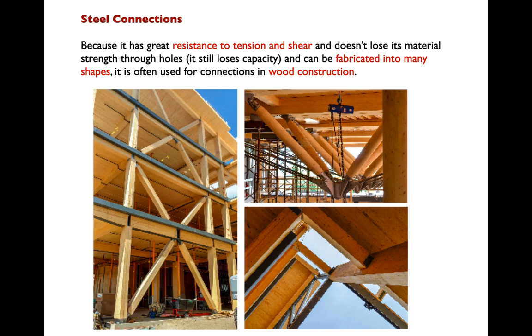But one of the things that wood is not particularly good in is shear. If we're trying to connect two pieces of wood with a pin, if we put a big tensile or compressive load on those elements, the wood is going to shear, the pin's going to pull out or kind of slice through the wood before the timber element itself fails. And so when we're doing high strength timber, we very often find that we need to connect the timber to steel and then let steel do the work of connecting elements to one another.